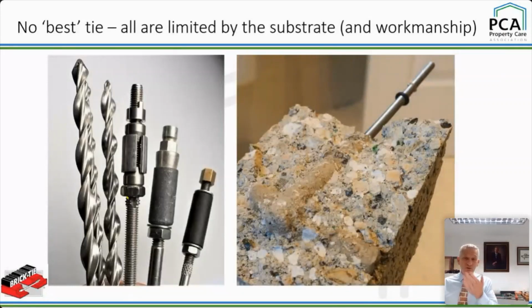All right. Got some samples of ties there, and I'm going to now cover the principles of fixing technology. Very basic. On the left-hand side, we've got helical ties. Lots of those around. You can resin bond them in, you can screw them into timber, you can friction fix them. And on the right-hand side, we've got the mechanicals. These are mechanical expanding ties, expanding to grip the hole.